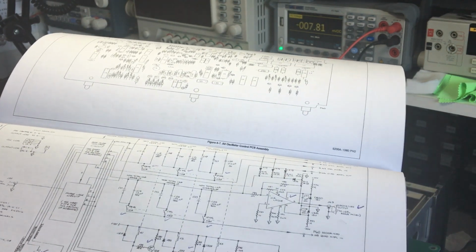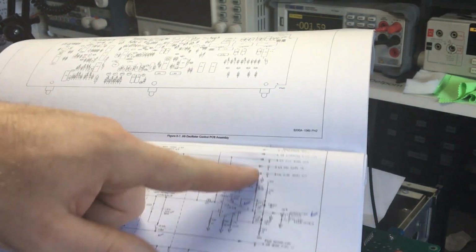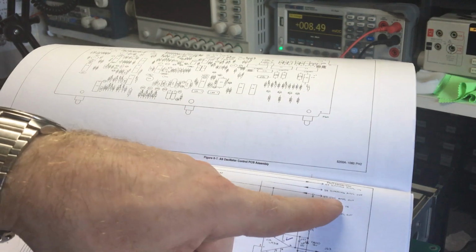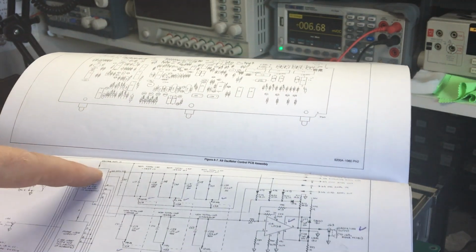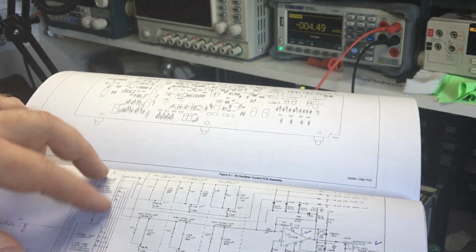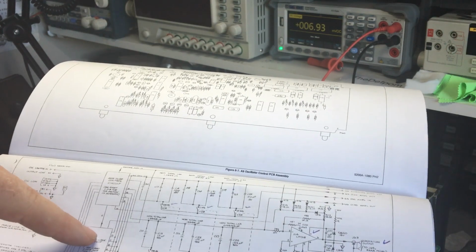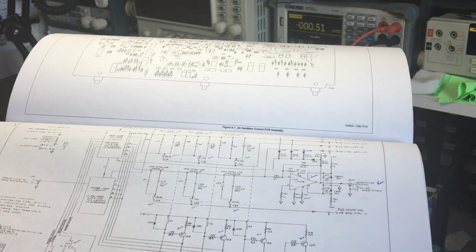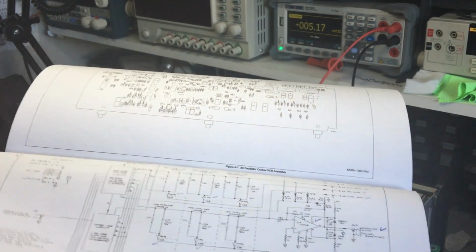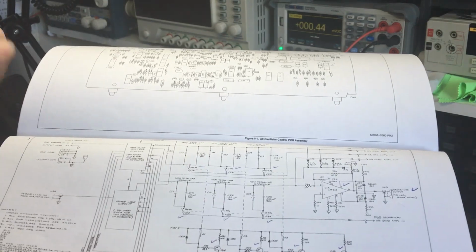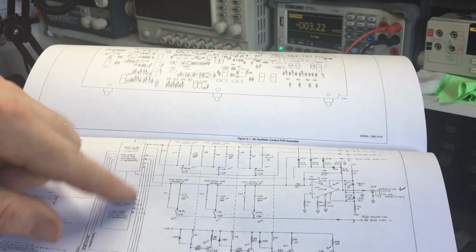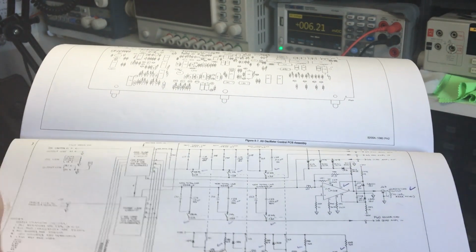And what I'm looking for, well, I've lost it. Oscillator amplifier out, which is the feedback from the oscillator amplifier. So that comes into here, splits off to both sections, and then they both feed back. So it could be either one of these units is causing a problem with the oscillator not working. My suspicion is actually with this one here, but we'll find out, because right now on phase lock, I'm changing the switch around, nothing's changing, and that's external input and internal input. So I'd say it's probably not that one, but probably that one. We'll see.